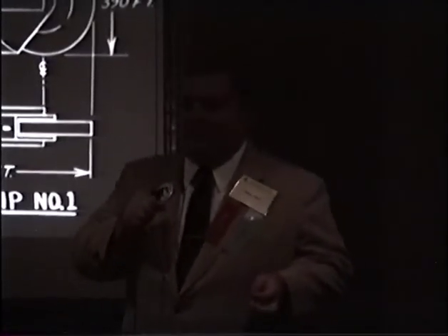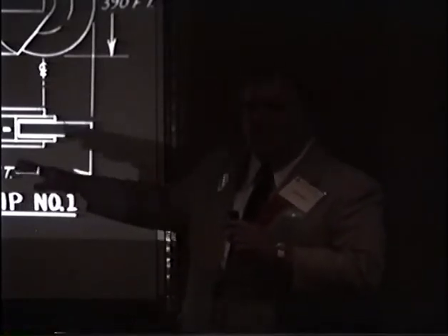You use your fuel flow rate basically to set your maximum thrust with whatever your highest K factor is, and you vary your K factor because you can finely control that, because you've got at least 3 different things you can control electronically, which is to say the field strengths on your coils, the switching frequencies, and the frequency ramp, which is increasing switching frequency as you go down the tunnel, because it gets faster and faster and faster as you go.